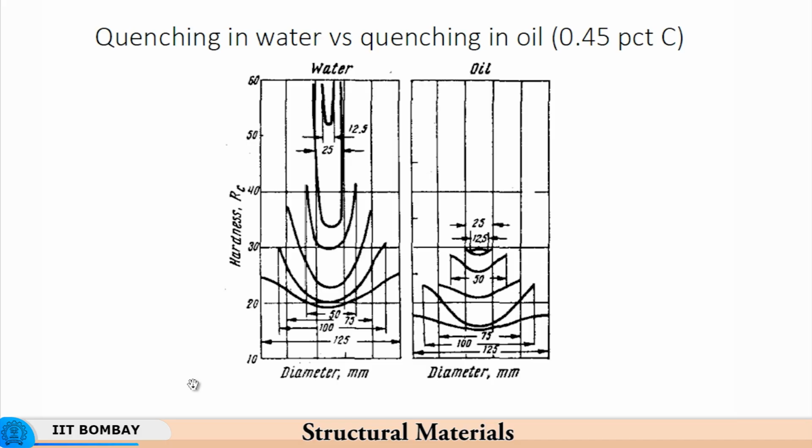Now, when you have quenched it in water, as the diameter continues to increase, the hardness distribution becomes shallower and shallower from the surface to the interior.